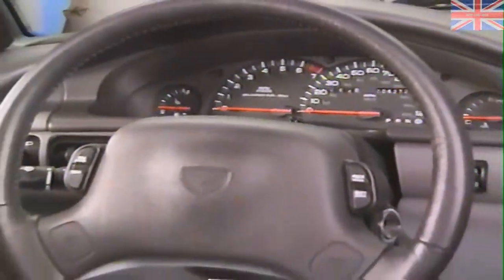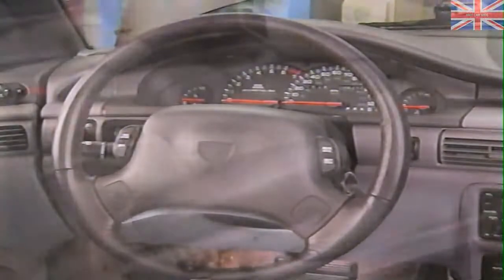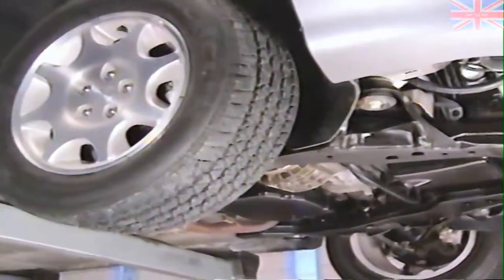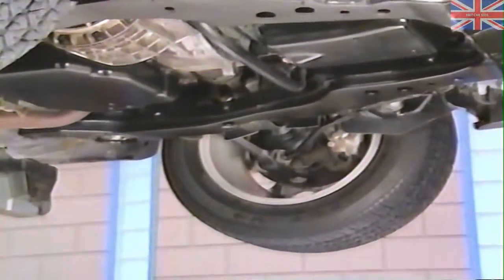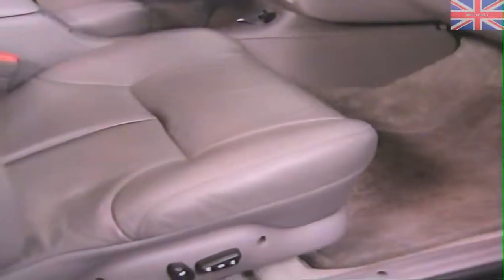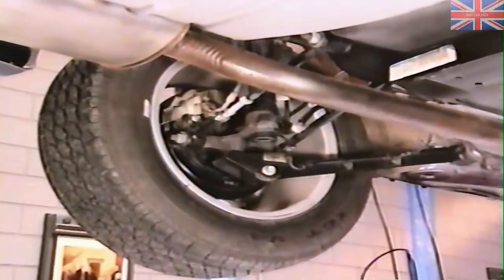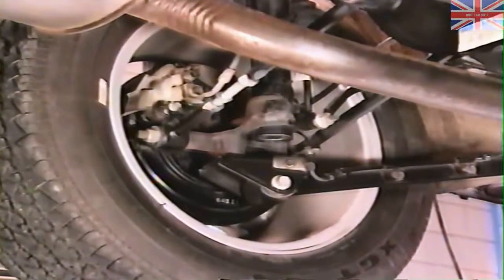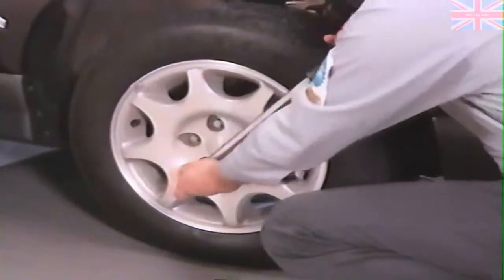It's a good idea to identify whether the shake symptom vibrations are felt in the steering wheel or if they are felt in the seats and floor. If the vibration is felt in the steering wheel, the problem is most likely related to the front wheel assemblies. Vibrations felt in the floor or seat are most likely related to the rear wheel assemblies. This may not always hold true, but use it as a general rule when isolating problems to the front or rear. The first check is wheel and tire installation.